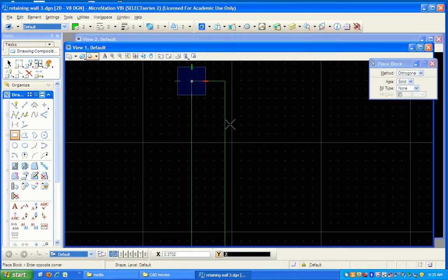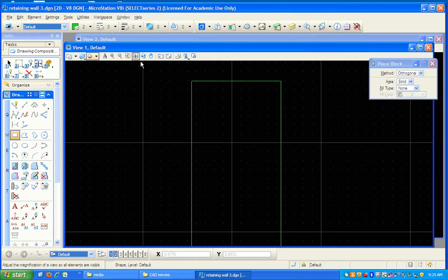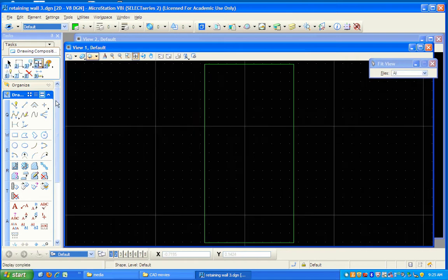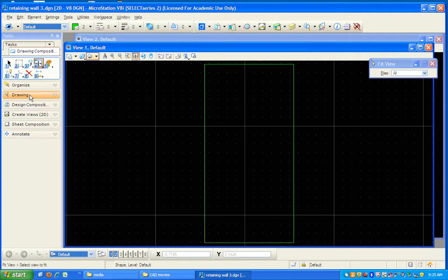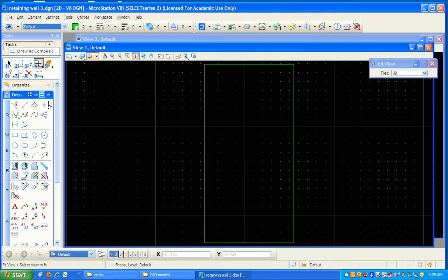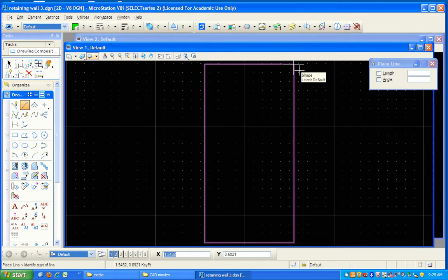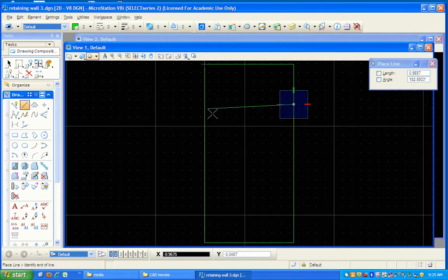And it's 2 meters high, as I said, and 1 meter wide. Okay, and we'll zoom in there. And then the cap itself is 450 millimeters thick. So let's draw a construction line reference from the top. So tentative snap, origin, and we're going to come down 0.45. And we want to do orthogonal drawing, so hit the return and snap to the top corner.